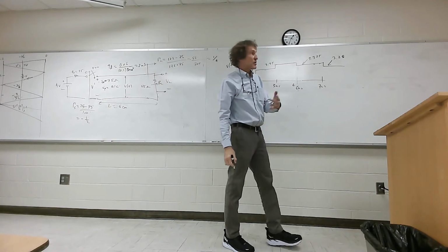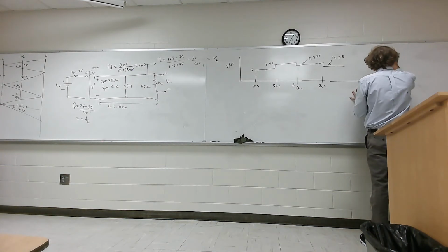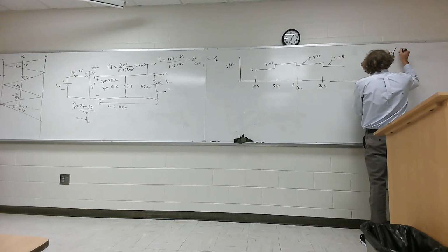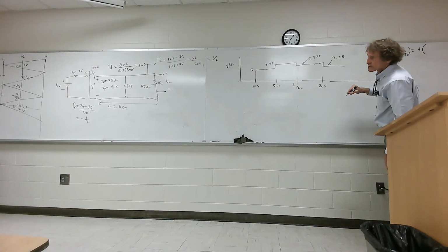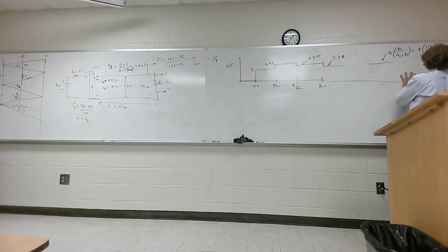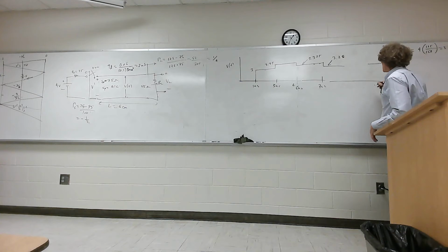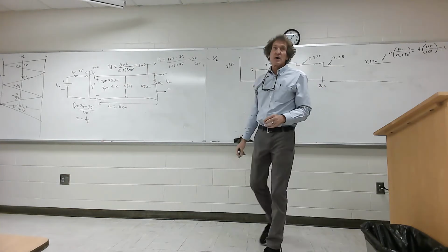Now, let's just take a look at where it's going to go way out here. It's going to asymptotically approach a value, and that value is going to be simply Vs times R load over R load plus Rs. For myself, Vs is 4, R load is 125, and that'll be 125 plus 25, 150, right? And what does that come out to? 3.32? So this would be 3.33 volts, and you can see we're bouncing around, asymptotically approaching that.